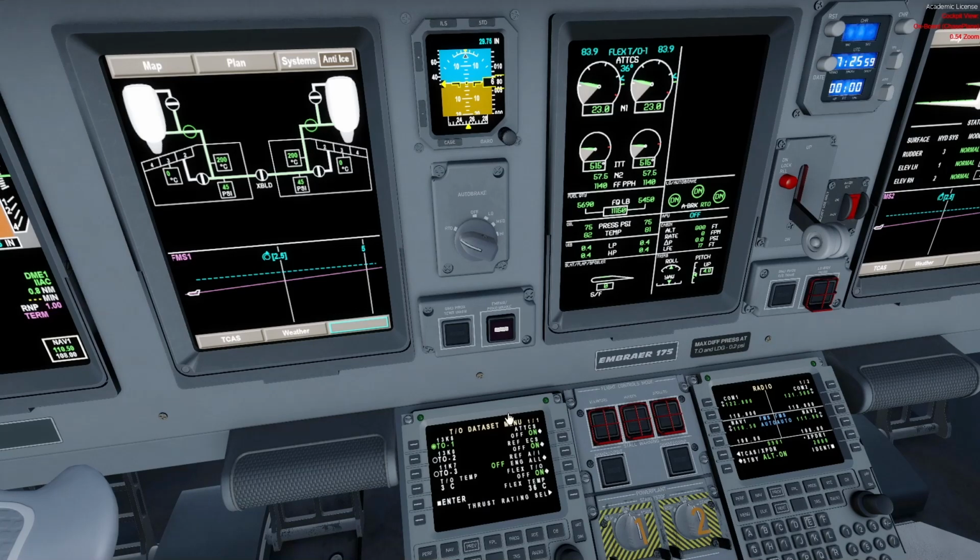It's not the takeoff dataset menu that's governing, nor can the ice detectors give me much information. It's especially prominent when you land on a perfectly nice day at an airport that has some snow on the taxiways, for example. The snow is contaminating, and by the way, this is an addition to what I stated earlier about what is ice condition during taxi. Also, when the surface that we're taxiing on is contaminated, is it wet or is it snowy or something like that. So in order to avoid the ice accumulating on the engine, we would want to turn the anti-ice on. So how would we do that?